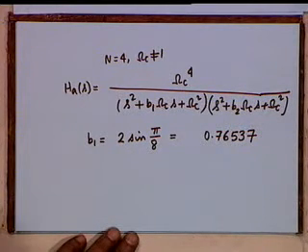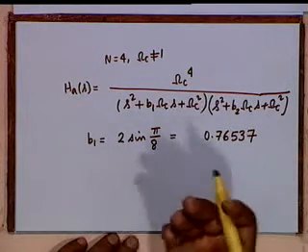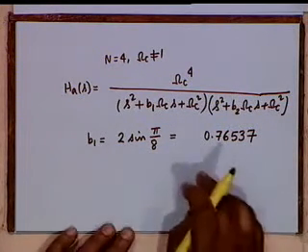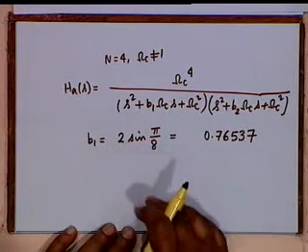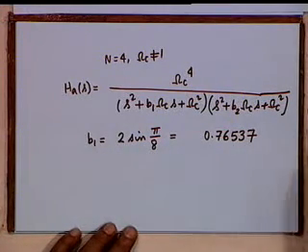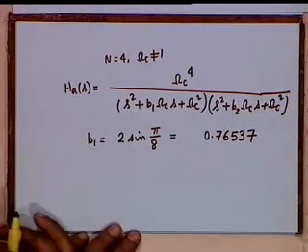If this filter is going to be used for design of an IIR digital filter, then you better take care of these constants to as many decimal places as you can. Do not make truncations unnecessarily, because you shall end up in trouble. Quantization error adds further to the errors and may make the filter unacceptable.